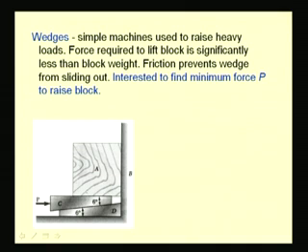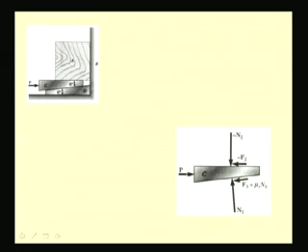So, let us mark this on the free body diagram. So, we have this block and the free body diagram of the wedge. Since at both these contact points this wedge C is trying to move from left to right, these frictional forces oppose the same and thus they are marked from right to left. These are the normal reactions, and for the impending case this can be related to the normal reaction using this coefficient of friction mu s.